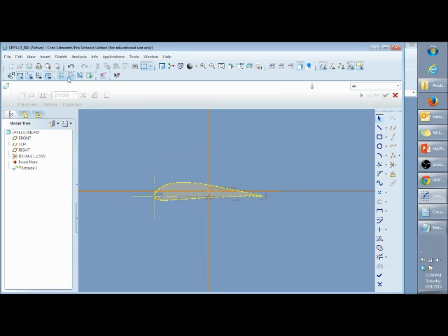This one will tell you if you have any open ends within your sketch, which will highlight in a different color than the normal sketch, red at work for me, if there are any free floating ends, which you need to delete because you need to have a closed loop. That's where this one comes in. It'll highlight a shaded area if it's a closed loop. Pretty simple. It tells you if everything's all good.